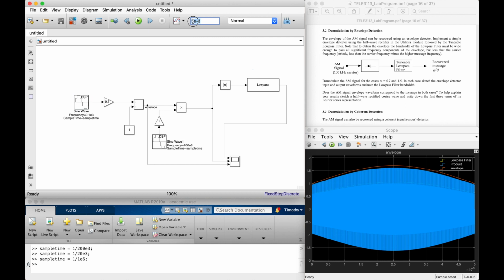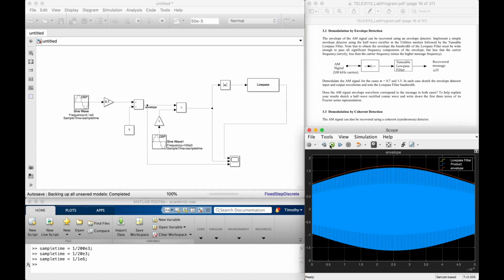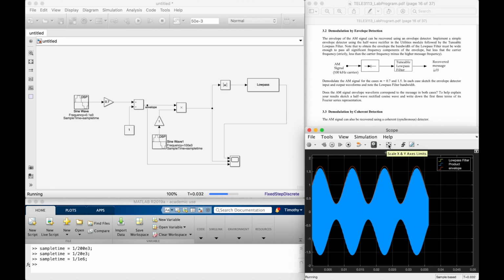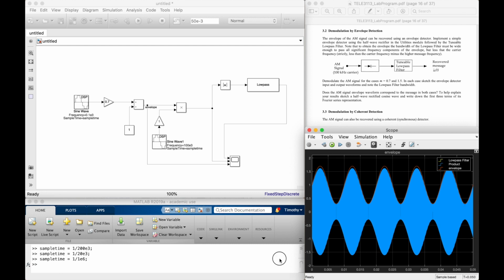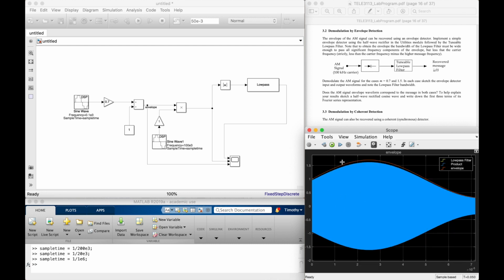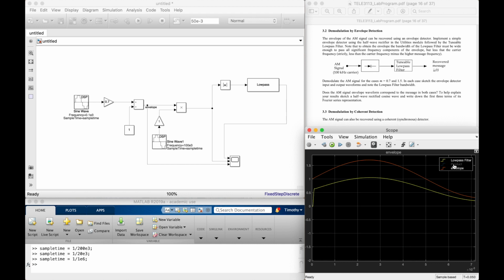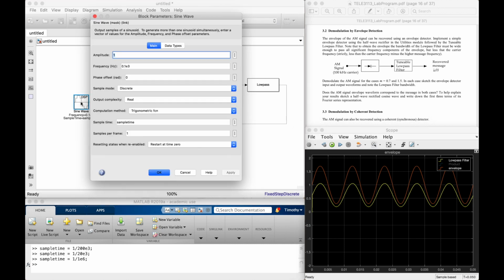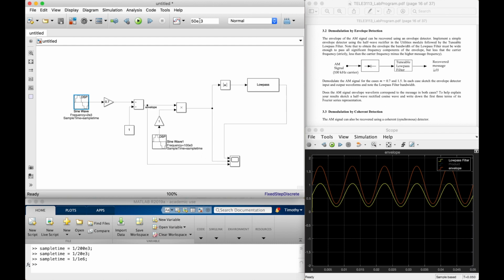And we're going to have to increase this tenfold now. Great, and if we zoom in on this now, let's get rid of the product. So now we can see there's actually not as much phase. So for lower frequency signals, there'll be less phase shift. That's how our phase response can be visualized. So we'll just change this back to 2 kilohertz. Okay, we'll change this back to